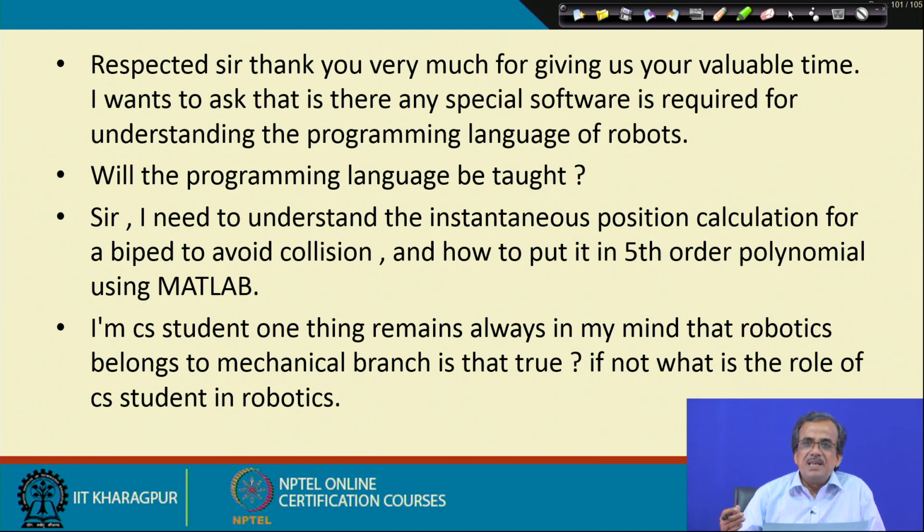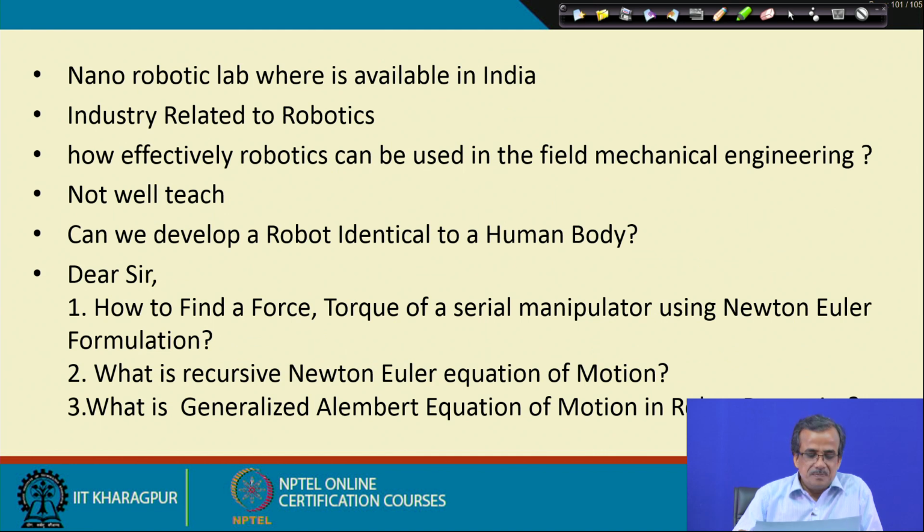So, trajectory planning has to be done, and the way the robot takes the movement, it will try to take the optimal or near optimal path in terms of power consumption or energy consumption. Now, if you use move in place of move S, there is a possibility that it can still follow the straight path. It depends on whether that is the optimal in terms of power consumption. But if you give the command move S, it is bound to follow that straight path. So, I think I am clear.